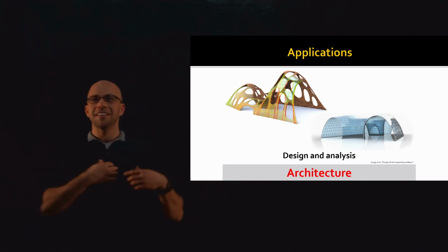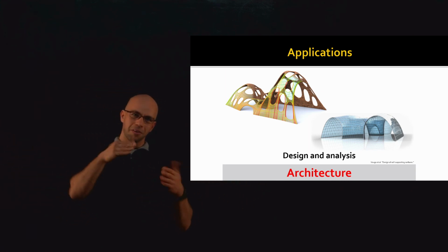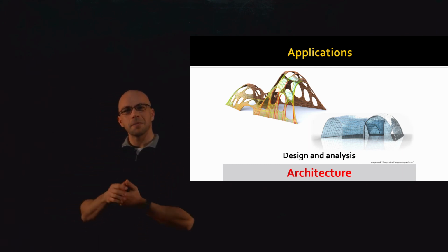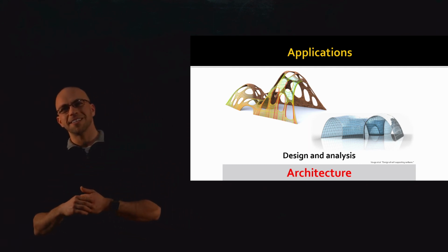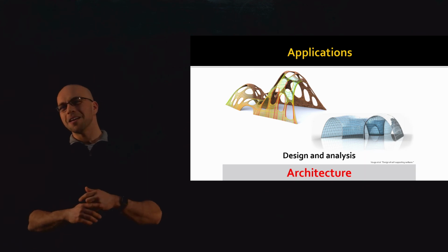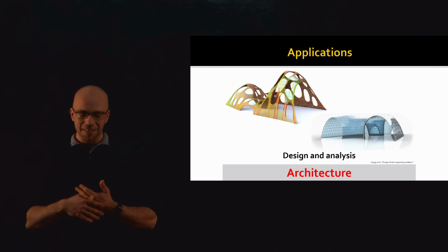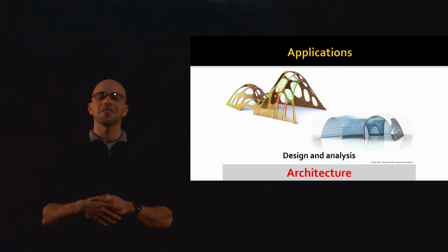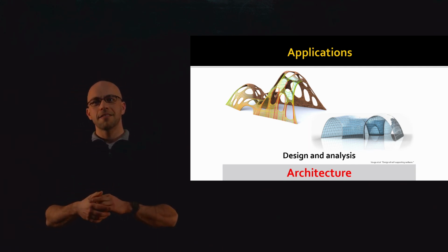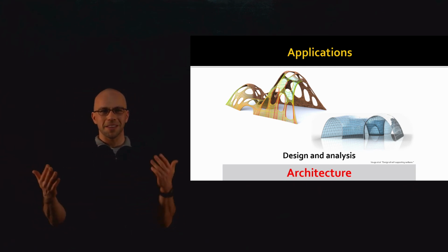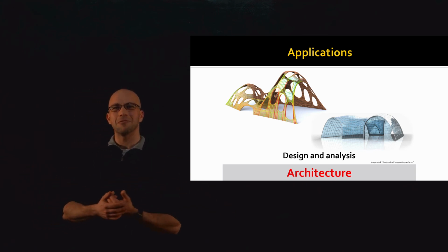The second easiest to manufacture windows are what we would call developable, which would be like making them into a cylinder, something that I can get by bending the glass but not stretching it. And then the most complicated ones are curved domains, like spheres or saddles that actually have intrinsic curvature. And so manufacturability actually tells us something about the geometry of the objects that we might want to make in our architectural application.